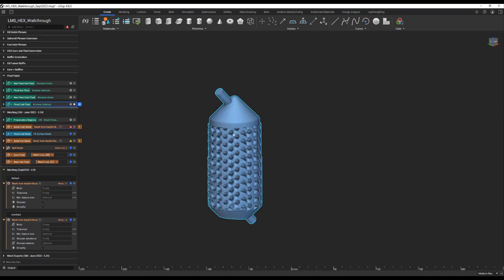We don't have to preserve the sharp edges within the TPMS structure itself. First, it's inherently curved, so it's going to be difficult for the algorithm to preserve those edges without causing self-intersections or some other mesh quality issues, but it also takes more time. So the first thing we'll do is set up both of these mesh blocks and go ahead and click compute.